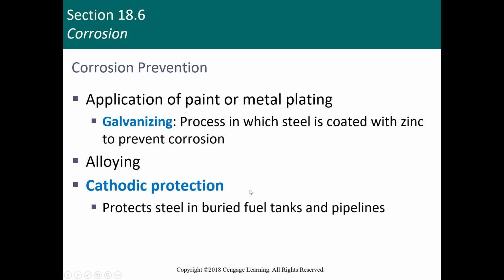Cathodic protection. This is actually the major way you typically protect steel in things that use a lot of steel, okay? So with alloying, you can make very, very good stainless steel that does not corrode very easily, but you would not want to make something like a fuel tank or a pipeline out of it. It would be incredibly expensive. If you have to, sure. A lot of water mains are made with this, with plating, with a surface of rubberization agent over the top of it.